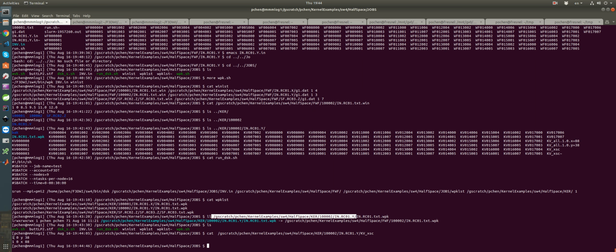So we are looking at 0 means P kernel, right? 1 means S kernel, S sensitivity. Right? And then we have only one window, so only one WPK, right? It's not frequency dependent, so it's broadband cross correlation. So it's just one window, one WPK. So 0 is WPK, and then one cross section is set at y equals 38, and one cross section is set at x equals 88. Again, these numbers are after grid decimation.